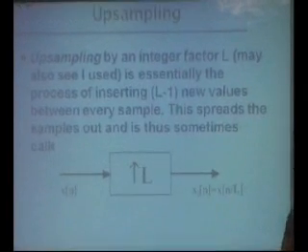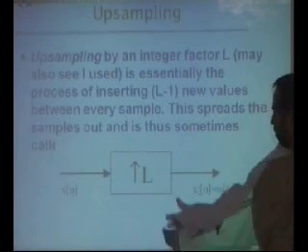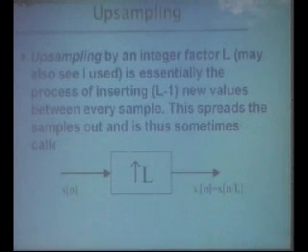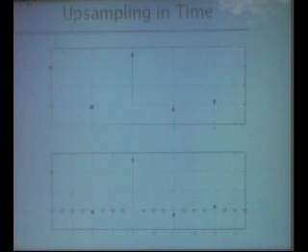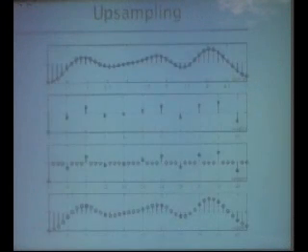So upsampling is where you upsample by L by inserting zeros. The same question comes up: why are we multiplying with so many zeros, why do you insert zeros and then do all of that? Inserting zeros and then passing it through a filter which requires many multiplications, right?